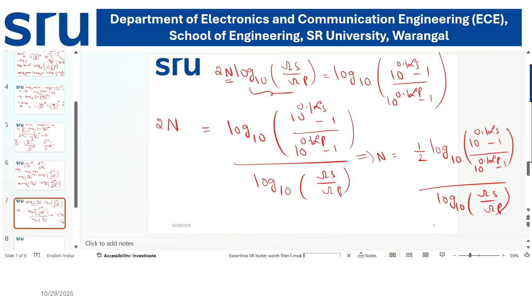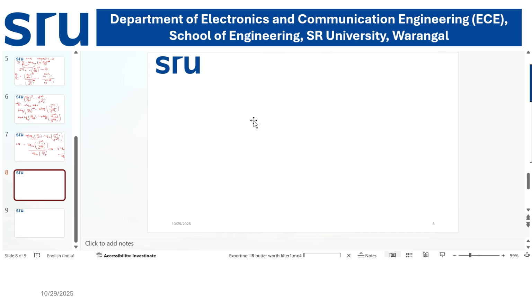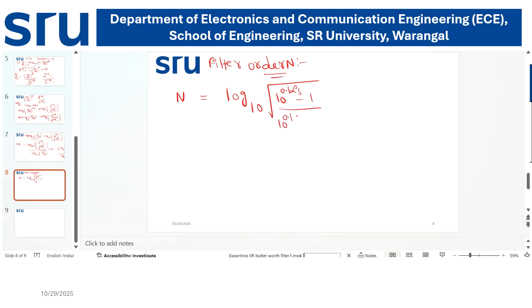Now this 1 by 2, if I take it to the inside of the log, therefore the n value, the order of the filter, we can find as n is equal to log base 10 of square root of (10 power 0.1 alpha s minus 1) by (10 power 0.1 alpha p minus 1) divided by log base 10 of omega s by omega p.